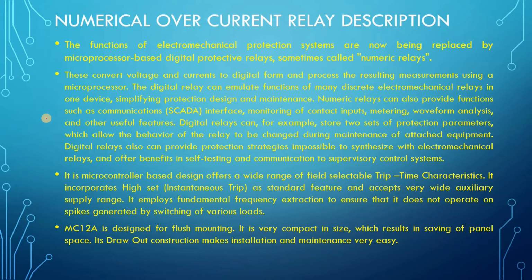Like, you might have heard of some distance relays used in transmission lines right now. The Micom relay is generally what it is called. That relay can act as an overcurrent relay, as an arc fault relay, and as so many other relays. This one relay is able to operate as many relays. One relay will protect whole transmission lines.